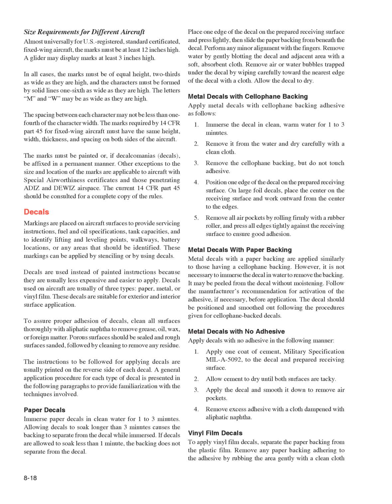Metal decals with paper backing. Metal decals with a paper backing are applied similarly to those having a cellophane backing. However, it is not necessary to immerse the decal in water to remove the backing. It may be peeled from the decal without moistening. Follow the manufacturer's recommendation for activation of the adhesive, if necessary, before application. The decal should be positioned and smoothed out following the procedures given for cellophane-backed decals.